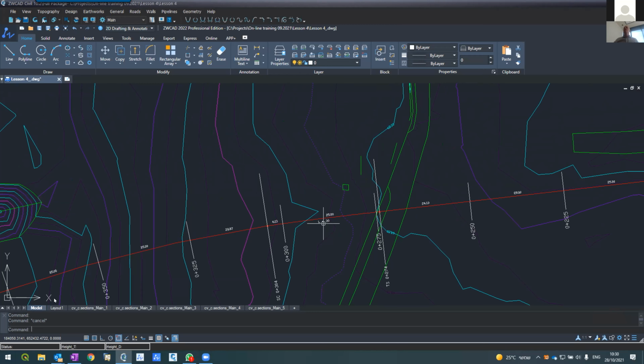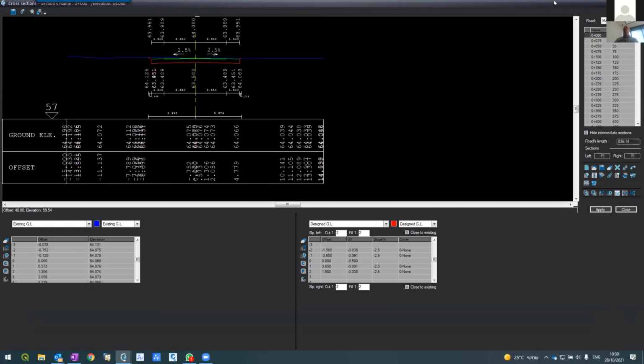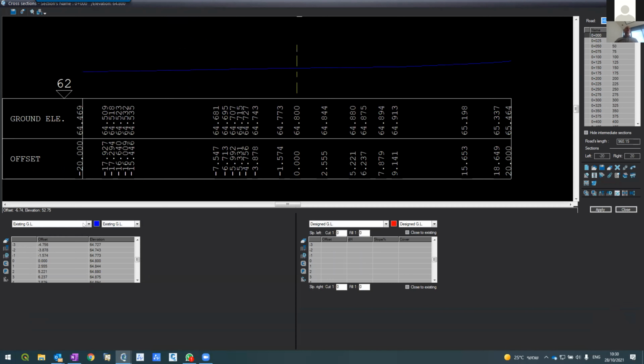Okay. And let's go to road, not main. Flip to the road which I'm interested in, highway HW. Okay, this is the road. So first of all, I change this to the structure. And I start at 0, 0, right? Which is the ground level. And I will start with the left lane. On the left lane, I want to create a sidewalk.